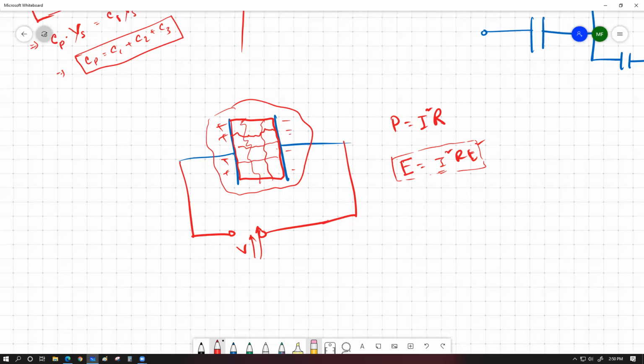What do we mean by maximum voltage? What we mean is that there is a certain maximum voltage for which the capacitor was designed. For example, capacitors which we use in the ceiling fan for our house are AC capacitors. They are pretty large. They can handle a pretty high voltage, 220 volt AC. But the capacitors used on the motherboard of a computer are extremely small. They are very small capacitors which are plugged in. Depending upon how much voltage you are going to handle and how much current you need to pass through it, you can change the capacitor's shape, size, material choices, and so on and so forth.